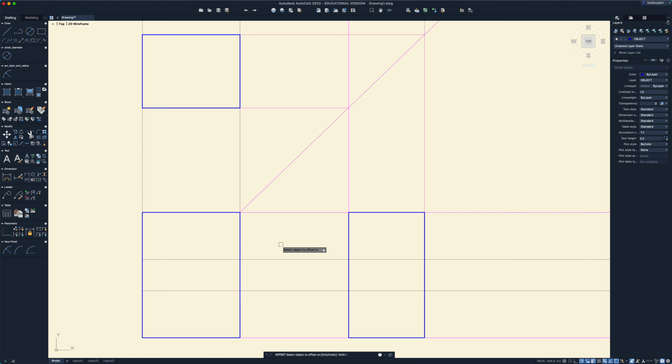And again, on the front view, this line moves to the left 120 units to give us the edge of that top piece, and this line right here will move to the right 120 millimeters to give us the top edge, which will go down to the center at this point and back up over here. So again, I'm going to go into offset, enter, 120, enter, and I'm going to move this one over and that one over, and that gives us those points.